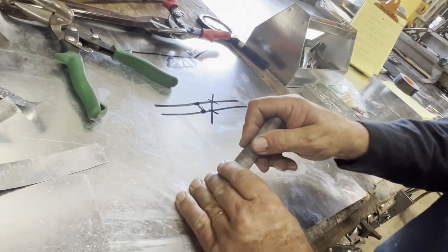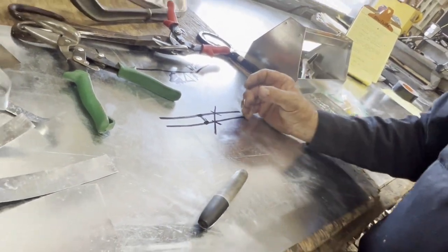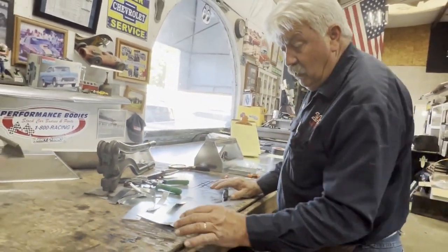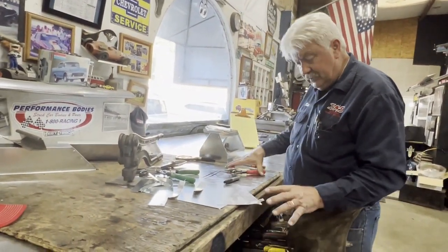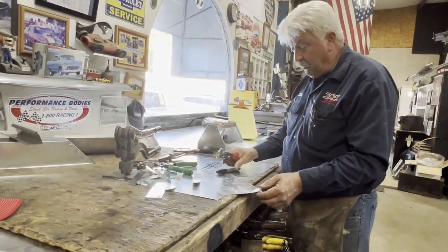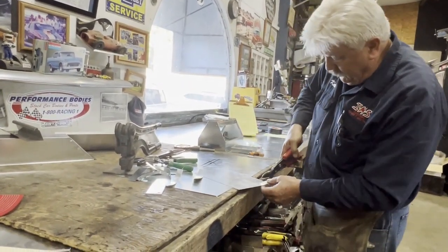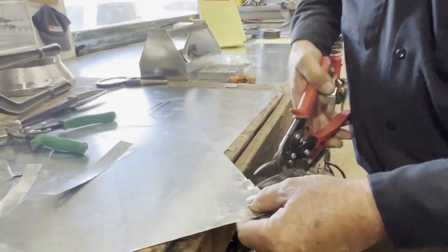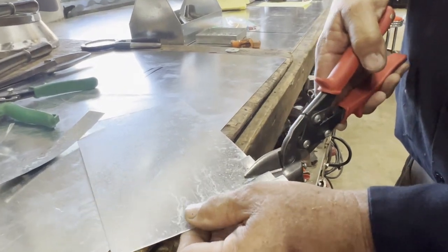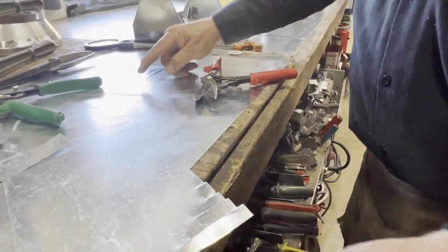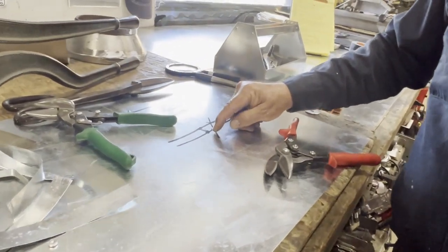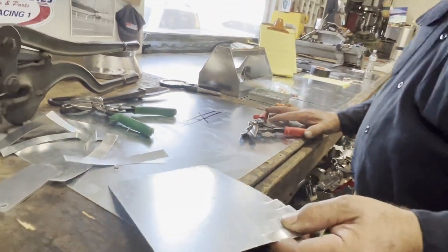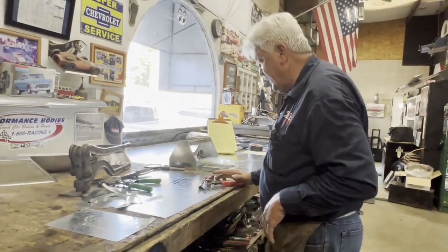So I've just added more energy requirement, and if you want to try it out, you're going to see that your snips will not appreciate your creativity if you hold it at an angle. Either way, whichever way you want to hold it, always hold the snip perpendicular to the work, and you're going to make the shortest possible cut through the metal. We don't want to cut at an angle. That's just going to make more work, and honestly, in the end, it never works good.